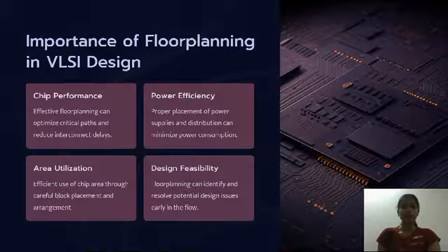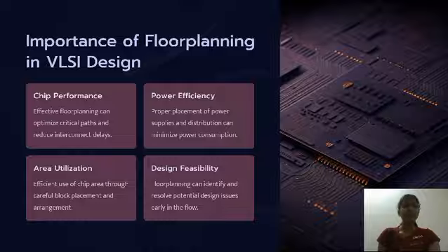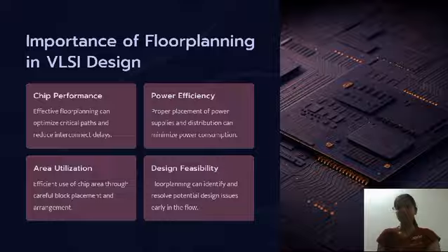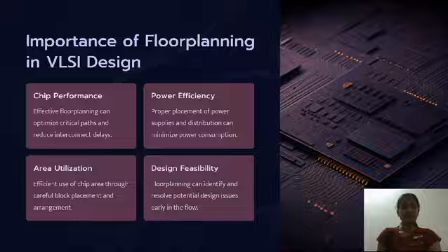Then we have the importance of floor planning in VLSI design: chip performance, power efficiency, area utilization, and design feasibility. Chip performance: effective floor planning can optimize critical paths and reduce interconnect delays. Then power efficiency: proper placement of power supplies and distribution can minimize power consumption. Then area utilization: efficient use of chip area through careful block placement and arrangement. Then design feasibility: floor planning can identify and resolve potential design issues early in the flow.